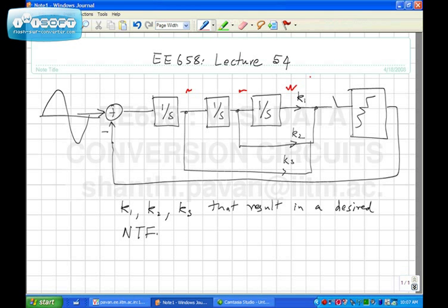And the operation of the modulator is already complicated enough without having to risk figuring out what will happen to the modulator if one of these integrators saturates. There is already saturation in the quantizer. So if the integrators saturate, at least what you say is you don't know what could happen.